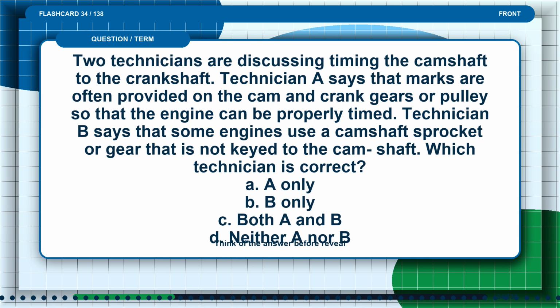Flashcard 34. Two technicians are discussing timing the camshaft to the crankshaft. Technician A says that marks are often provided on the cam and crank gears or pulleys so that the engine can be properly timed. Technician B says that some engines use a camshaft sprocket or gear that is not keyed to the camshaft. Which technician is correct? A, A only. B, B only. C, both A and B. D, neither A nor B. Pause and think of the answer before the reveal.